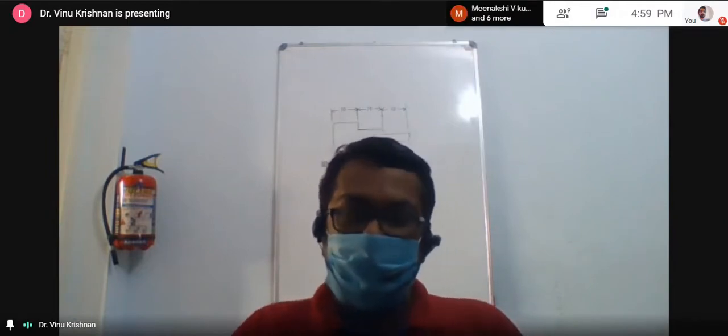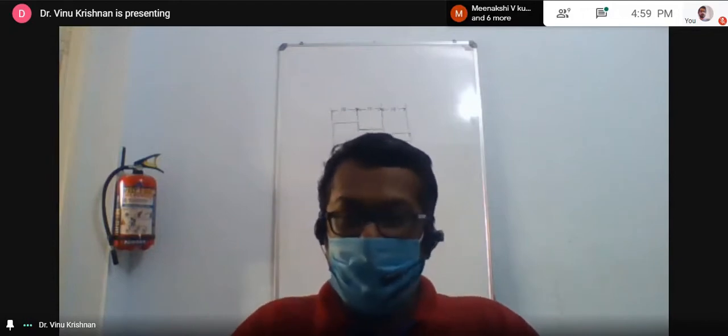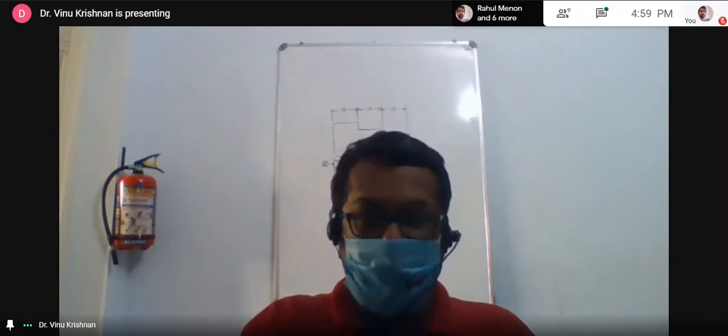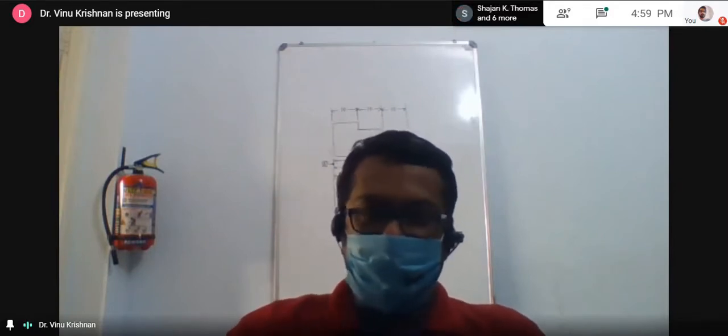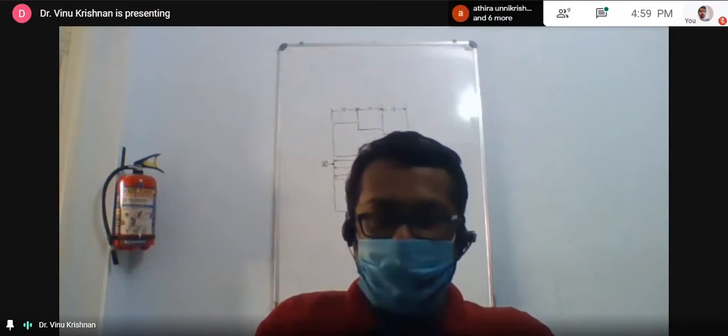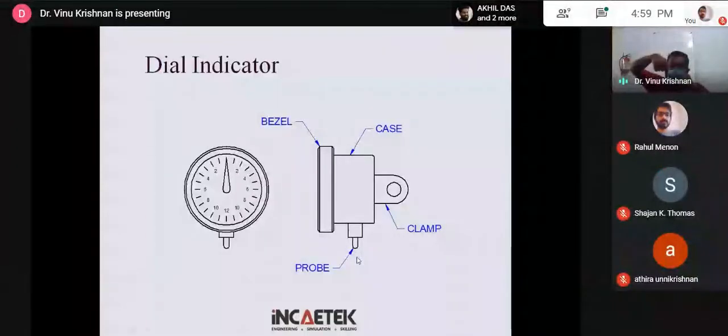Then runout. I'll tell you in a video. You might have seen the dial indicator, where you have a dial, a needle, and a plunger or a probe. If you put the probe on this surface, based on the finish or the shape, it will go up and down.